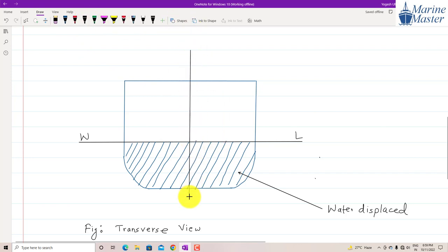First of all, this vertical line. Guys, observe. This vertical line denotes the center line. And how are we going to draw the center line? Bigger line, smaller line, bigger line, smaller line, alternating. And how do we denote the center line? An L, and inside the L, a small c.